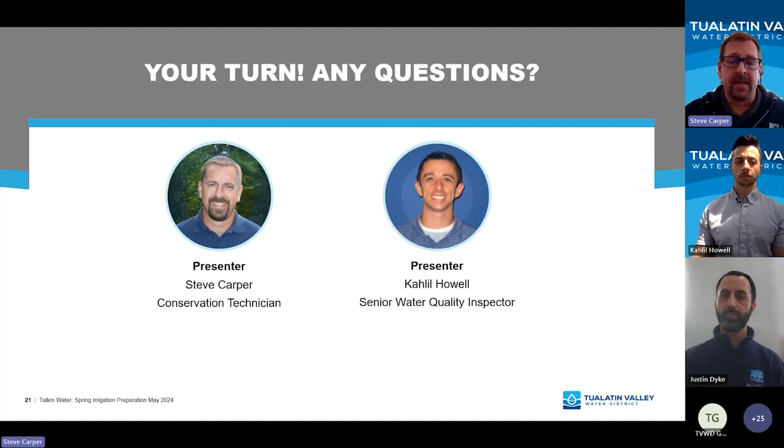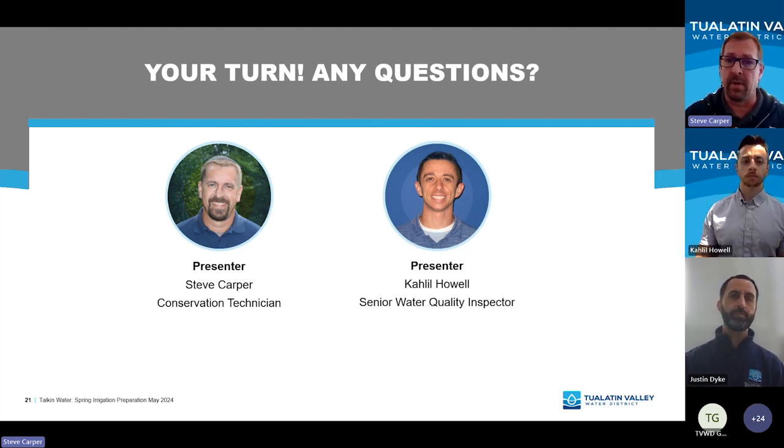Absolutely. Kind of jumping onto Cal's point about reaching out and using somebody that has a license from the Landscape Contractors Board, what you're looking for is a landscape construction professional that is licensed to do irrigation work. And in speaking to backflow devices specifically, that they have that backflow phase included in their license. Really important that you find somebody that's licensed and insured to do this type of work, so that you find somebody that's competent to do it effectively. It's not going to create more issues for you.